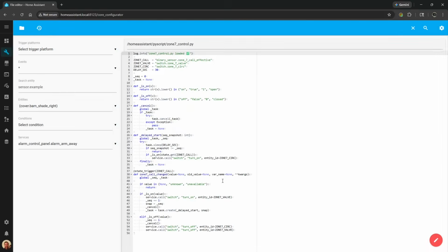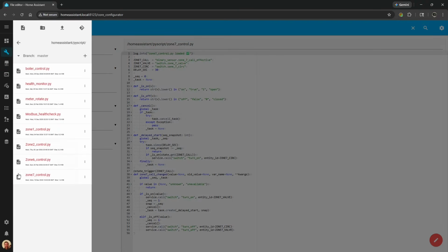Zone 7 is this one zone. It has a valve that is used to prevent ghost flow. And yes, they should have used a check valve, but whoever added the zone valve did it this way. This simply says when this zone is calling for heat and the pump is running, it sends 24 volts AC to the Taco valve, I think it's a Taco 571, and it turns the valve open. When the zone isn't being called for, it shuts it down. So simple as that. So these are how the main logic gets done.